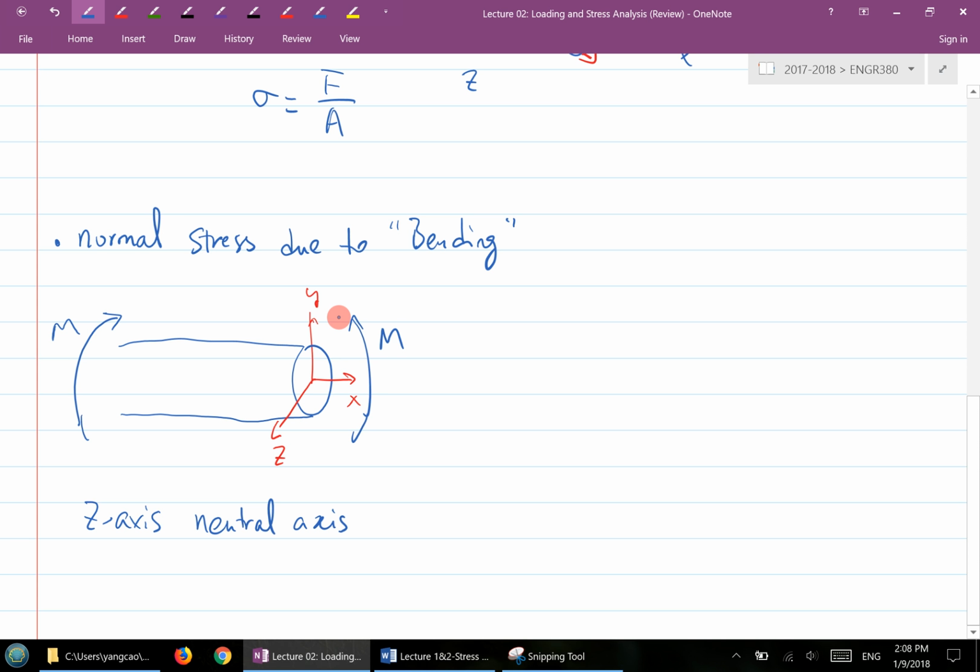Just like a force pointing in the positive axis direction is considered positive. However, when you come to drawing a shear force diagram, it's not like that. It's relative to the cross section the shear force is applied to. If it causes the cross section to go clockwise or counterclockwise, then there are these negative and positive signs. So just be aware of this.